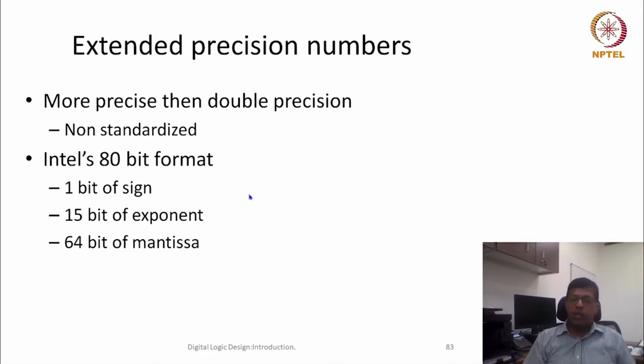So for example, somebody was designing a calculator. Because the parts of a calculator are not going to be used somewhere else, they were defining their own precision. So let's say your calculator was showing only 10 digits of a decimal number. So the precision can be decided accordingly. Similarly, let's say you're designing a computer which requires arbitrarily large precision, so you could use more bits for precision and exponent.